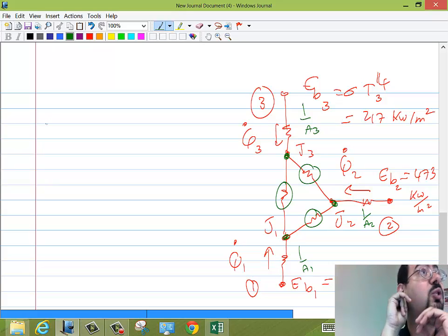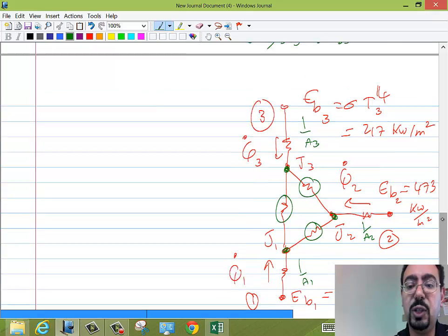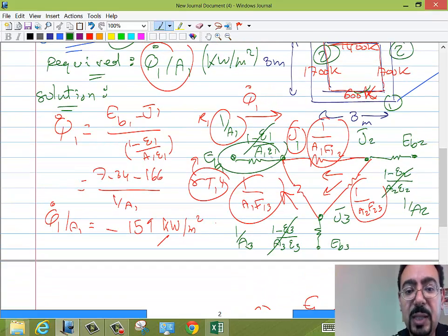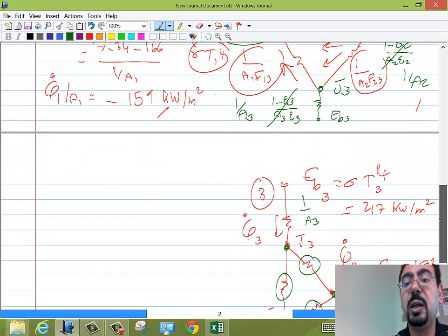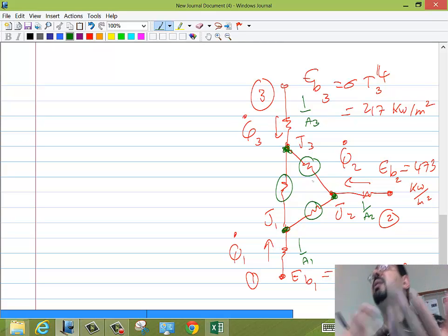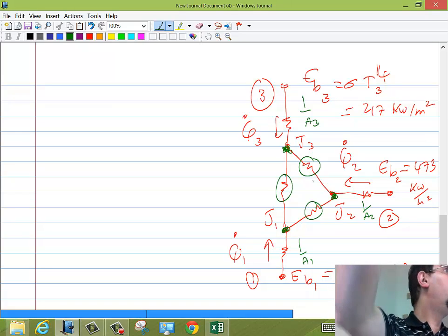if we get the resistance, so I'm solving the problem backward again. In the previous page I told you why I need my J, because eventually, separating this part, the Q would be this minus this, E plaque minus J1 over the resistance. That's why I need my J. So now to get the J's, we are going to just use at each node the fact that the Q, the heat transfer, will have to split.